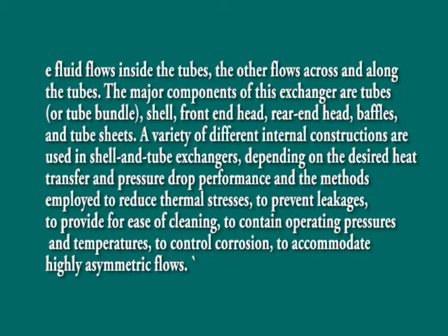The three most common types of shell and tube exchangers are fixed tube sheet design, U-tube design, and floating head type. In all three types, the front end head is stationary while the rear end head can be either stationary or floating depending on the thermal stresses in the shell, tube, or tube sheet due to temperature differences as a result of heat transfer. Figure 1 clearly shows the tubular heater.